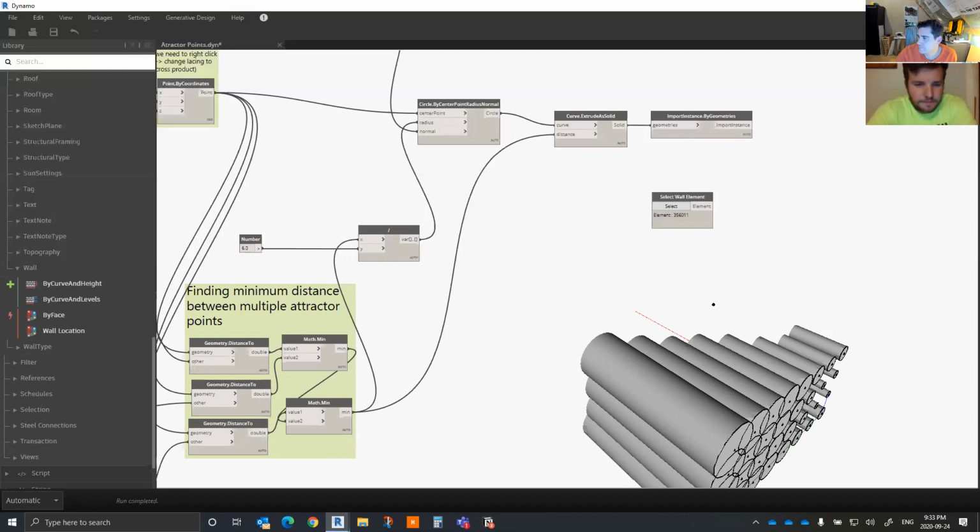Can you use Dynamo stuff like this within families? Like if you were to make a new family for a curtain panel, and then apply this to the curtain panel and do 5 options of it, and then take that to a larger facade as a whole. Right, so then you're playing around with panel A, panel B, panel C. And then you could do energy modeling on it.